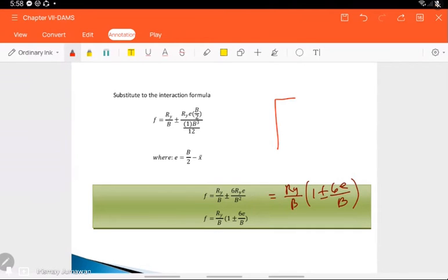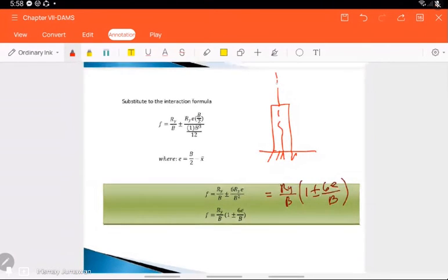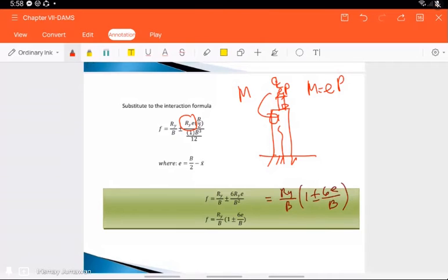So for example, if this is your structure, then you have here the center. Okay, this is the center. If you have a load there, you have an eccentric loading. So the moment there is equal to the distance from the center times the load. So that is the moment, E times Ry is the formula. So again, if your load is at the center of gravity,